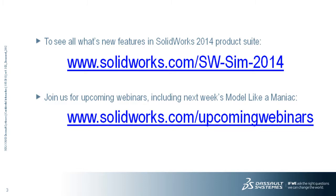Great. And then there is a question about, do you have to manually input each Toolbox fastener, preload, torque, and other fastener info? Regarding the new functionality of 2014, the Toolbox mapping, the goal is really, when you have already defined your Toolbox fastener in SolidWorks, to automatically use them for the bolt connector definitions. You do not need to redo the work twice.